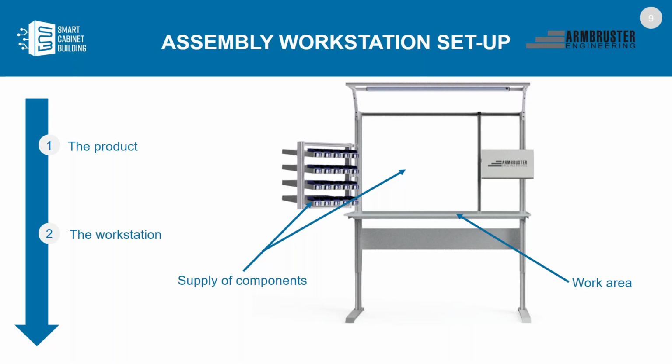So the second consideration is the workstation itself. The work surface should not be oversized because we want to avoid unnecessary storage space at the work area. With the table height, you should pay attention to the fact that the working height is always dependent on the workpiece and whether it is standing or sitting work, or even both. In addition, you should plan enough space for lighting and power supply.